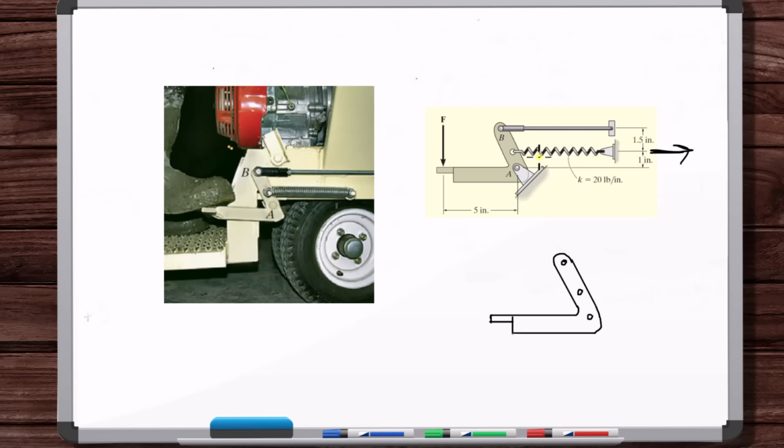So again, here they tell us that the spring is stretched and they tell us by how much. So we know the spring constant, right? You buy a spring and it'll tell you the spring constant. So we can determine the force from this spring. So you can't by mistake put this spring force acting to the left. That would mean the spring is in compression. You're going to screw up your problem. It's not going to tell you that you did that wrong because you're defining the problem. The knowns you have to get correct.